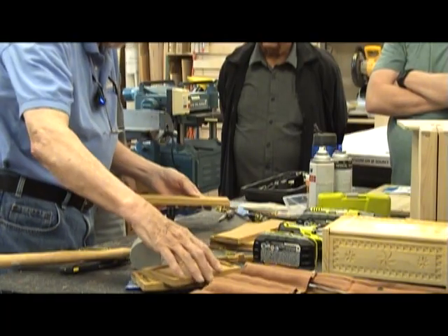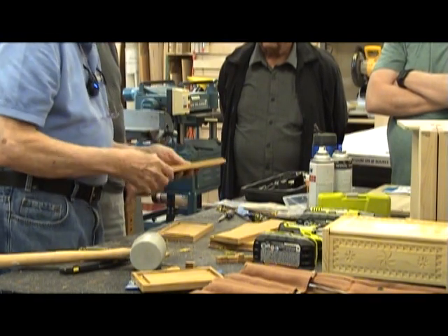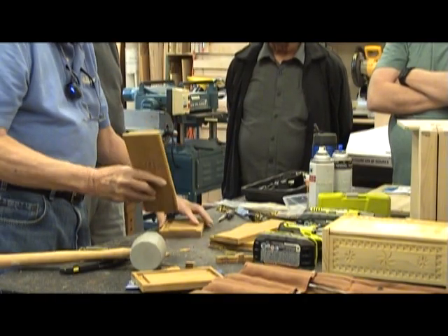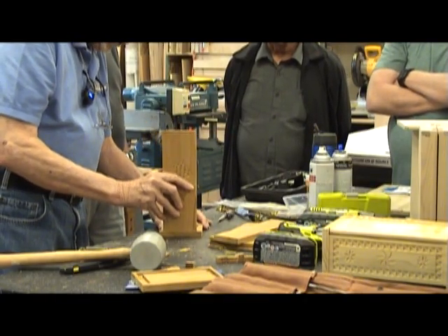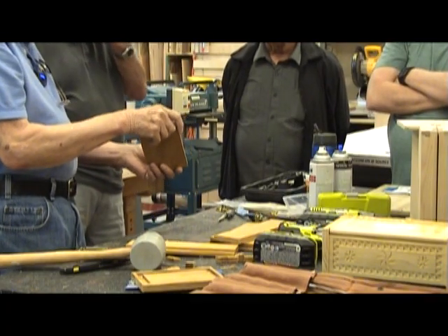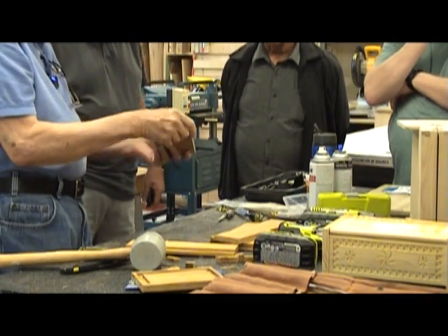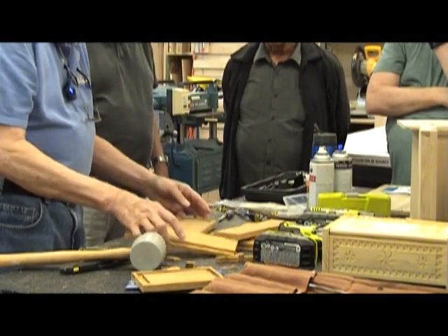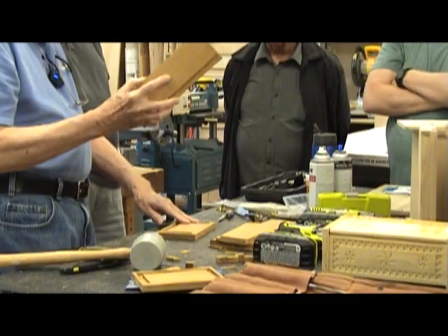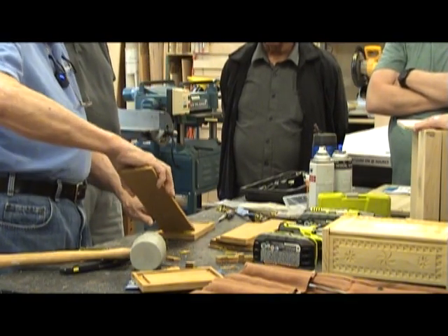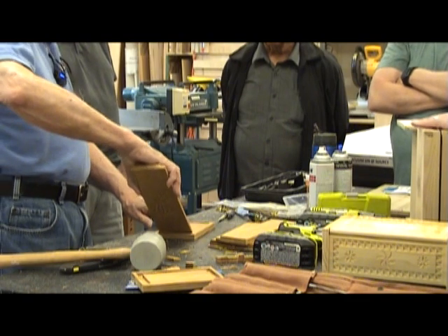It's questionable now whether this is going to fit into the mortise. There are two issues. The first is that the mortise is rounded off due to the bit, and second, the thickness we know is thicker than a half an inch, per the machine, which is exactly a half an inch.